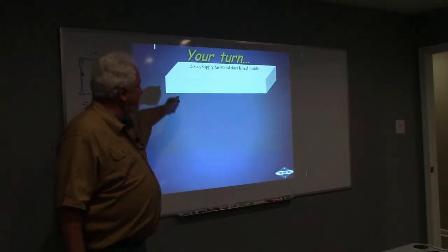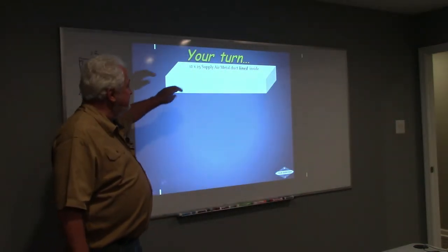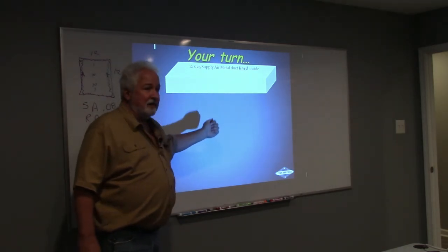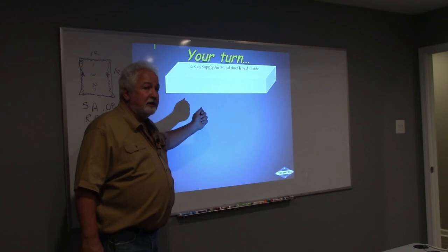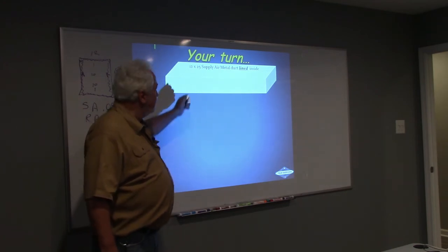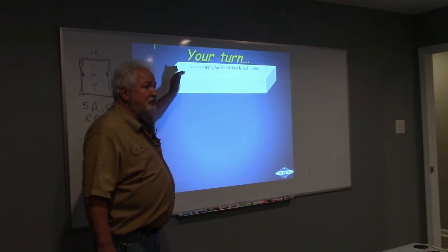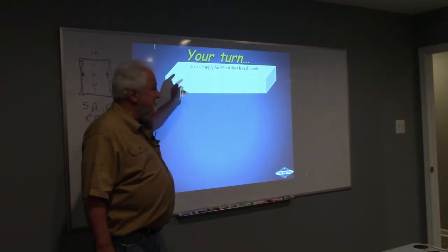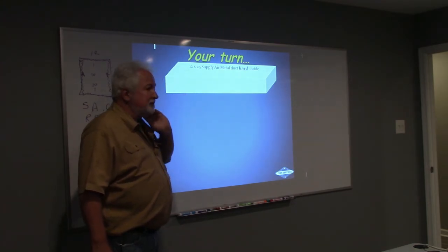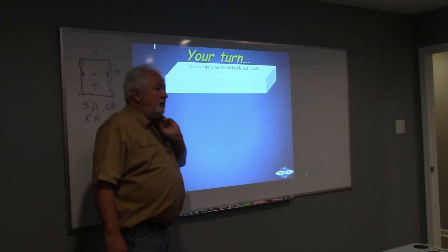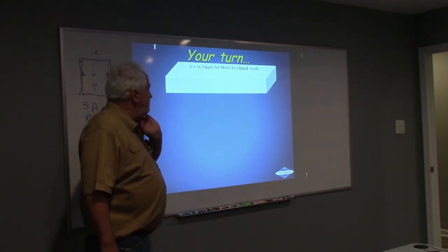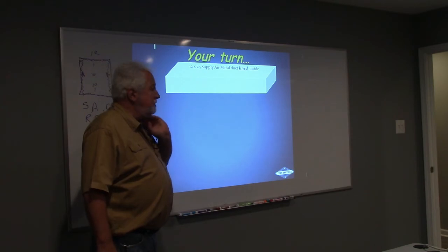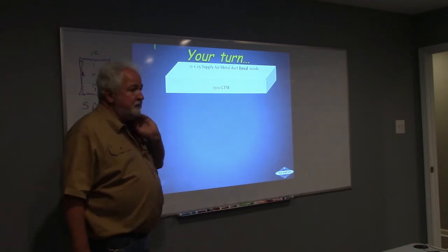Okay? You've got a 12 by 25 supply air metal duct, but it's lined on the inside. So duct with liner, where am I going to look at that? Very bottom, down at the bottom. Look at it down there with duct with liner. I got a 12 by 25. I'm giving you the free area inside that duct. It's lined on the inside. Supply is going to be 0.08. Absolutely. 12 by 25 lined metal down at the bottom.